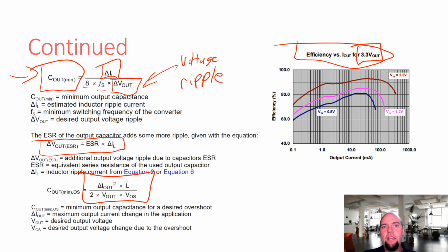Power saving modes. When things go to sleep, to low power modes, microcontrollers don't want to always be consuming milliamps of current. Your microcontroller probably is going to wake up, do something, go back to sleep. And when it goes back to sleep, it's 20 milliamps to 20 microamps. It could be 20 milliamps to 20 nanoamps, right? Some of them really sleep nowadays. So power save modes, low power modes, sleep modes.